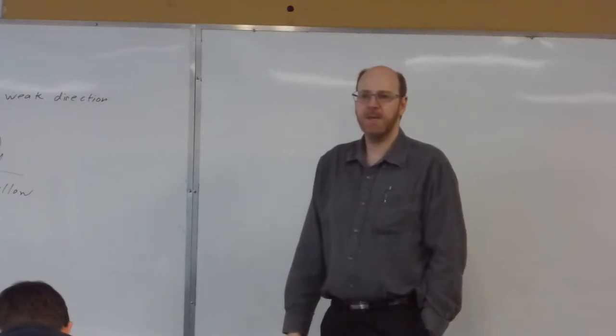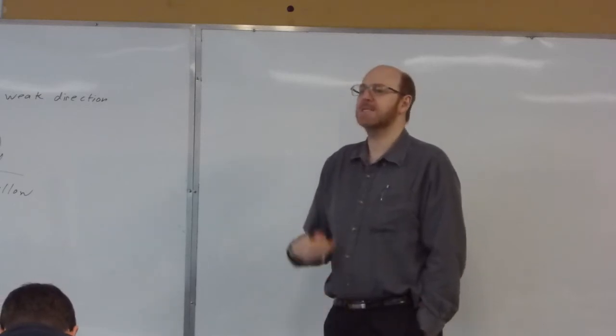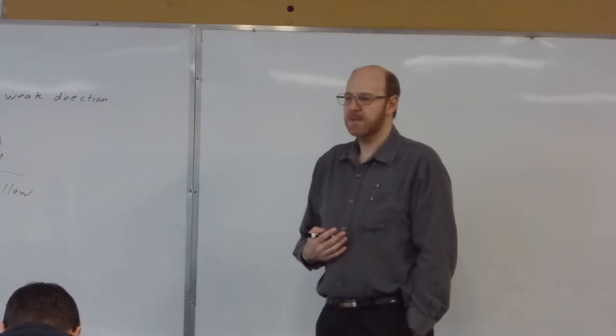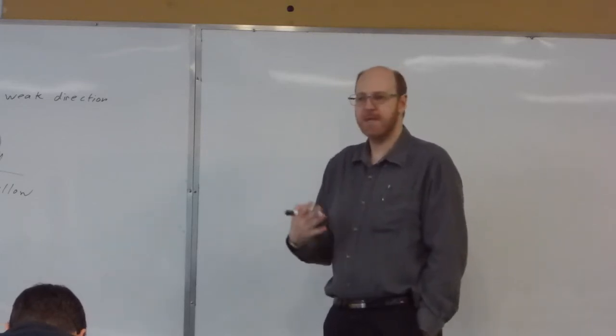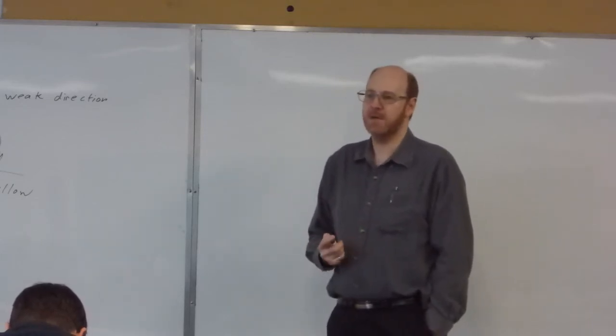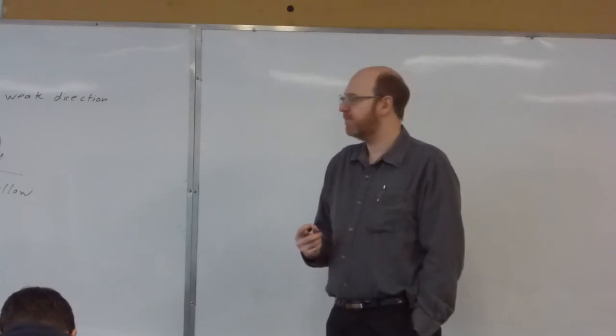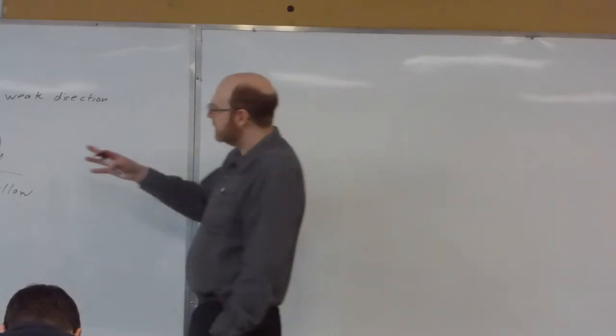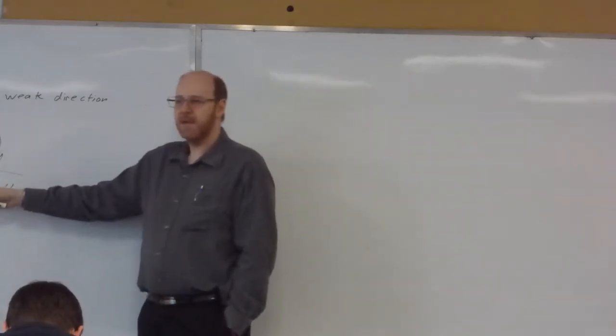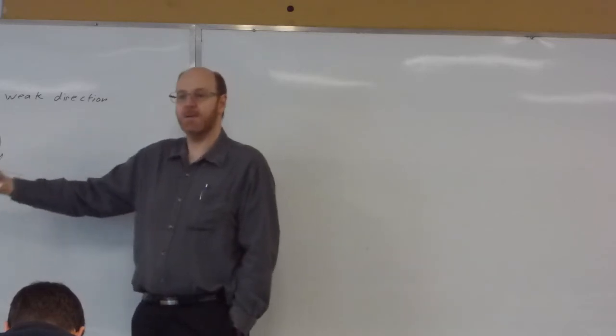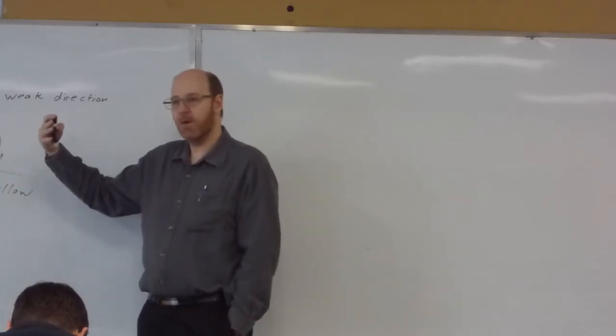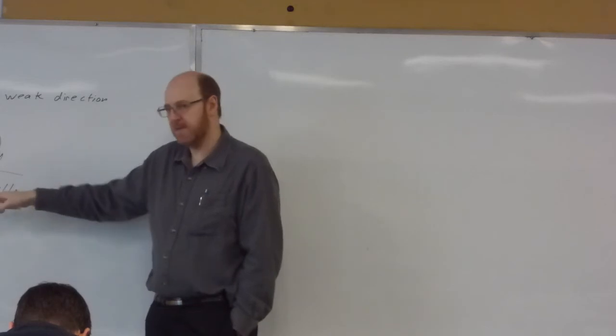The idea here is that we want to force any potential failure to be away from the brittle failure mechanisms. Right? If there is going to be a collapse, what we want to see is excessive deflection first, so that hopefully somebody will notice it and say, this doesn't look right, let's do an investigation. If we put a higher factor of safety on our connection details, then theoretically they can handle more load, so that means that we're going to go into plastic bending before we get to failure in our connection details.